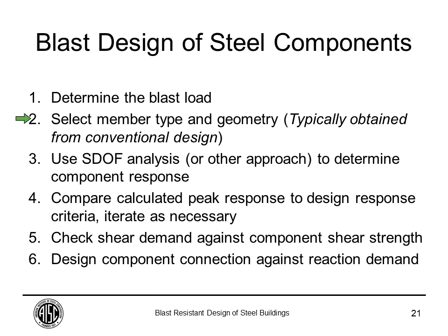So you can grab that design, you have some components and geometry that have been defined, and then you just analyze them against the blast load, and then you can tweak as needed in terms of connection capacities, spacing, member strength, to make sure that your structure is blast resistant.